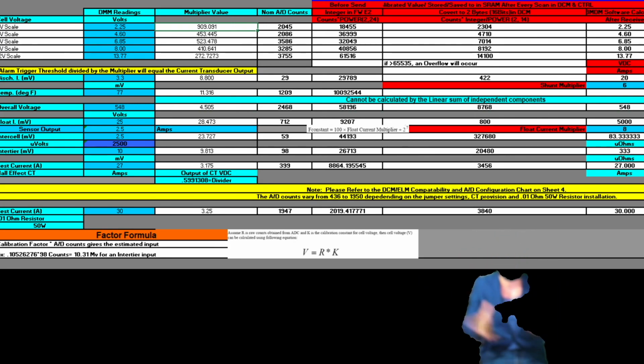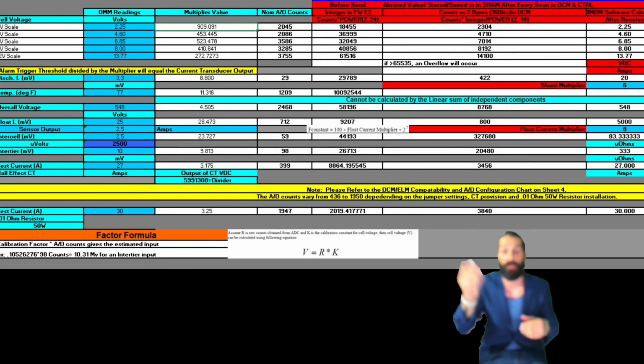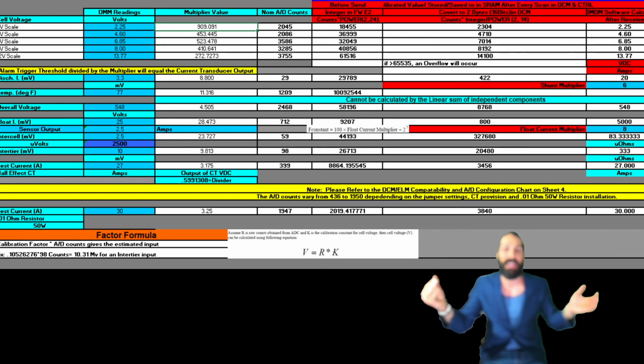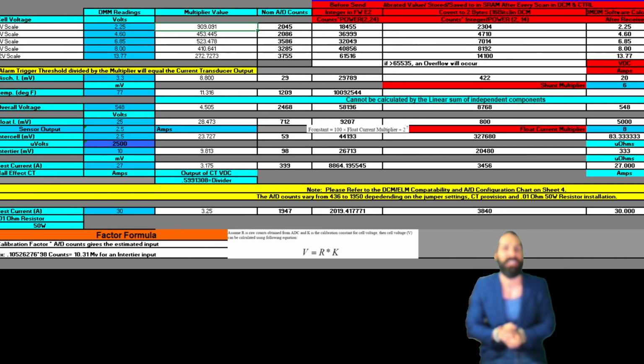In a parallel system, it's a little bit different, because if you have a battery failure in string 3 on cell 22, a lot of the string current from the discharge will flow into that battery, and that can cause something we talk about as thermal runaway. There's an International Fire Code section 608.3 that talks about tripping mechanisms for thermal runaway. I will have an entire video reviewing how to mitigate thermal runaway and the implementations of certain electrical design and mechanical switches, and normally closed, normally open methodologies that you can integrate effectively to mitigate this entirely.